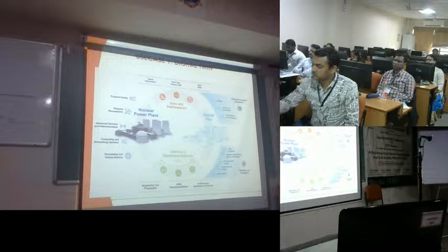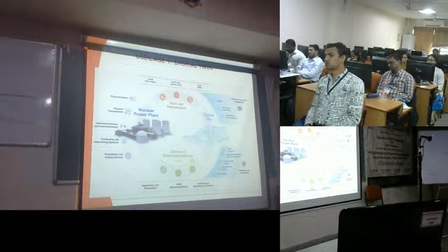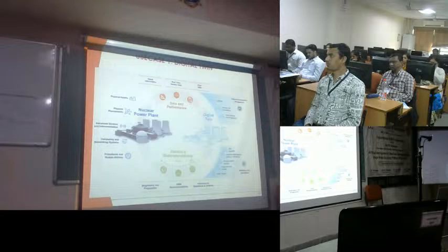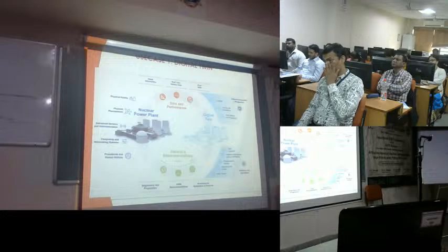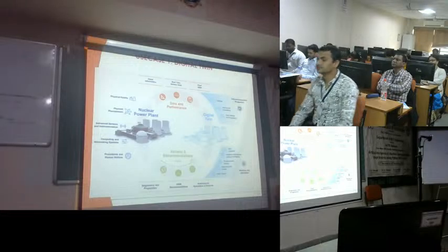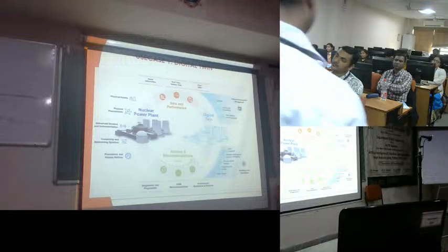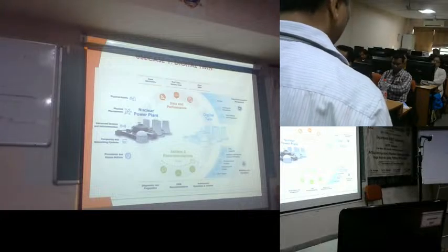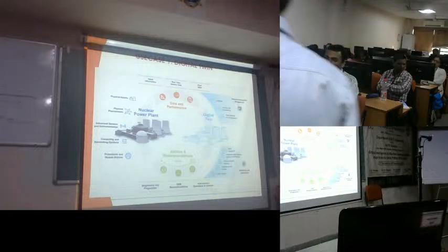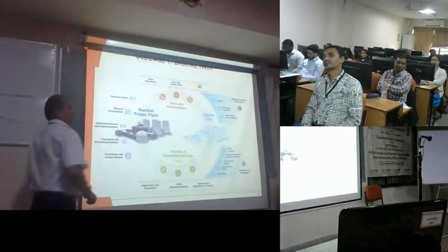Or the pressure of that particular tank, right? Or the temperature of the fluid, or the flow rate of the fluid that is flowing into the pipe. These are the different parameters. So we do have a lot of sensors: flow sensors, pressure sensors, temperature sensors, those are RTD sensors. And those sensors are also very interconnected, because one may require getting input from another sensor and passing output to the other sensor, based on which some processing needs to be done. So some sensors are smart sensors as well. And so you have to model all those sensors.